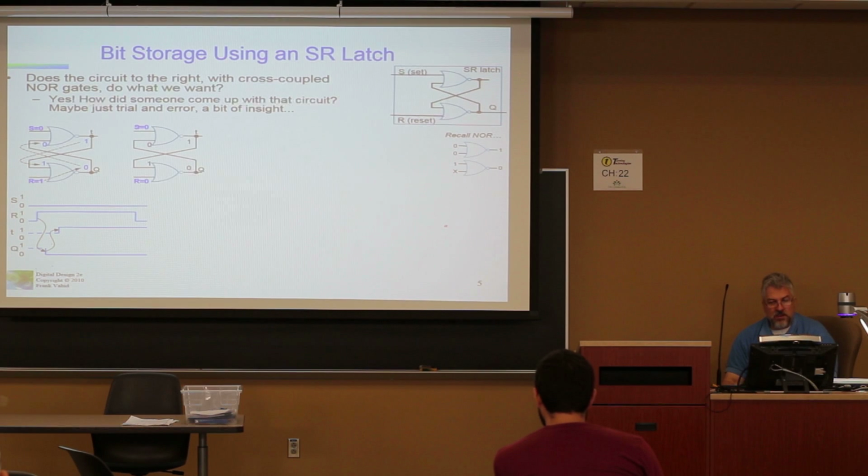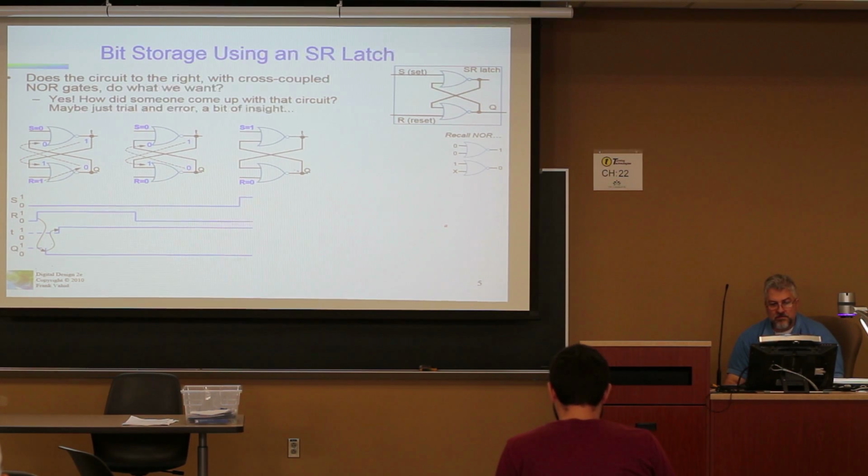But look at the neat thing we do right here. Let's say that we have S, and we move S up to 1. So now we have 1, and this output is a 0. 1 and 0, so now that we're changing S to 1, that's going to change this to a 0.